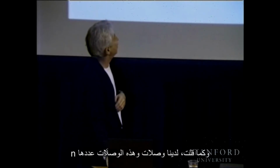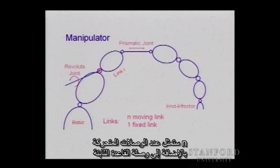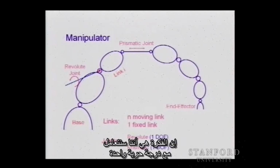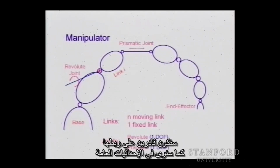So, as I said, we have links, and those links are n in number. We're going to call n the number of moving links plus one base link, the fixed link, and we have joints of two types, revolute joints and prismatic joints. So the idea is we are going to work with 1 degree of freedom joints, and this is interesting because knowing that, we will be able to connect these to the generalized coordinates, as we will see.